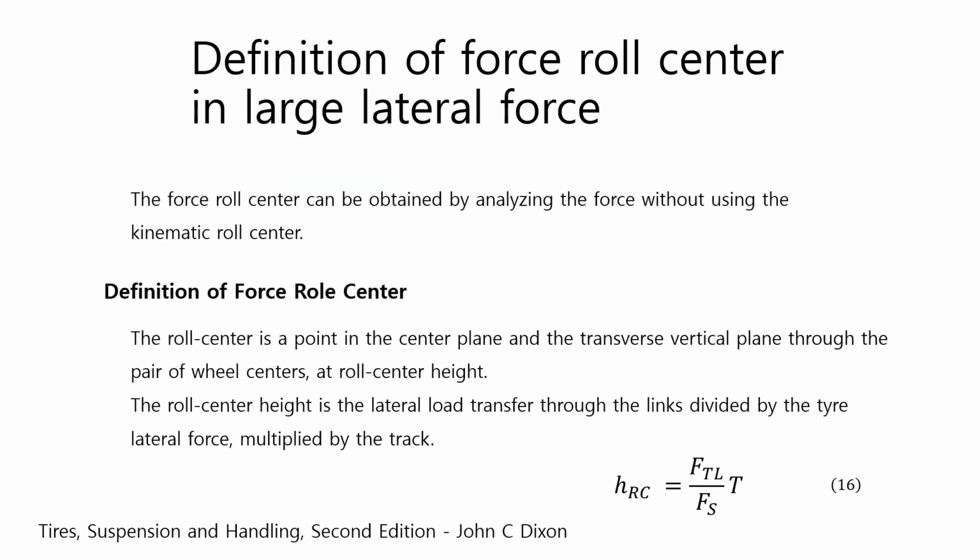Finally, let's summarize the definition of the force roll center under the large lateral force examined in this video. I've explained that the kinematic roll center is not a true roll center, and that a true roll center should not induce rolling motion in the sprung mass when a lateral force is applied to the roll center. Furthermore, I've explained that the lateral location of the force roll center must clearly represent the moment arm caused by the sprung mass, the location of the sprung center of gravity, and the roll angle.